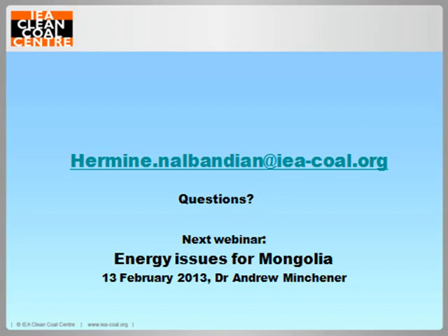But let me see, differences between trace element emissions in combustion and gasification reaction. The report goes into detail about not just that, but the pressure as well in both the systems. Emissions of trace elements in gasification is less than emissions in coal combustion or pulverized coal combustion. That is based on measurements. However, the measurements, as I said, of trace elements is rather difficult. The methodologies are not available except currently for mercury.